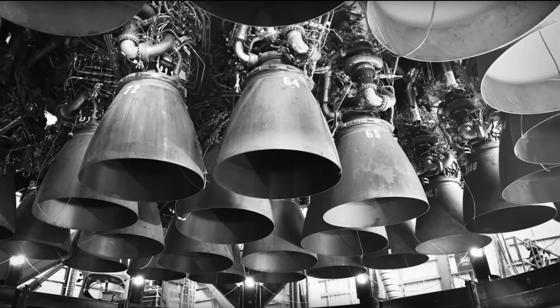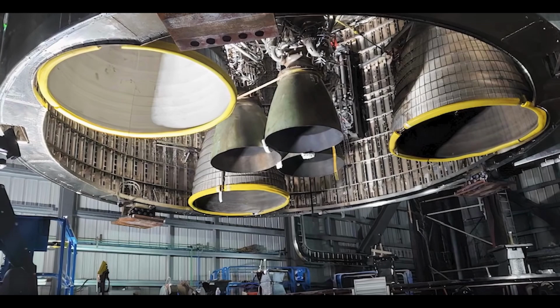Due to its designated field of usage, the sea-level variant finds a compromise between high thrust, low weight, and high efficiency. With an enormous thrust-to-weight ratio and a specific impulse of over 300 seconds, it fulfills these requirements perfectly. The sea-level variant makes up the center cluster and the inner ring of the engines on the Super Heavy booster and the 3 center engines on Starship. They are mostly used for the vehicle's ascent and especially the landing burn.